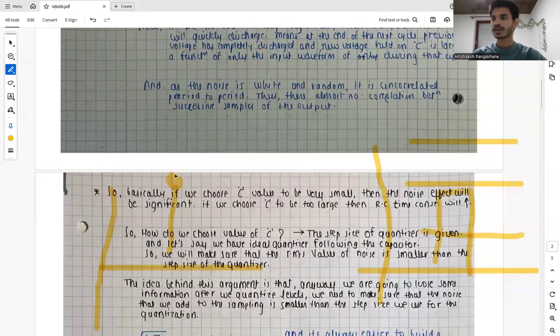So basically this is the value of that sample, but due to the noise which will sit on this Vin, the noise can go up or down by a little. Then we say that it might shift the quantization, right? Like it might shift the step. So we say that the length of this step should be really greater than this noise. So basically, this noise cannot shift the sample from one step to another and give us the error. That's what I mean.